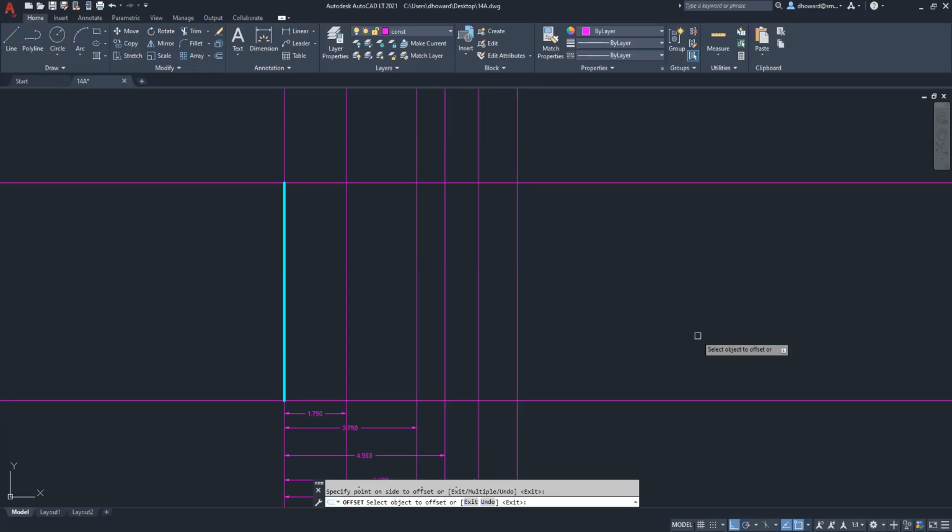It's 2 inches up from the bottom. So we'll say that is 2 inches up from the bottom. There you go. And then its center is 2 1/4 from that. So 2.25. That's the center of that hole. So those are the two big vertical offsets that we need.